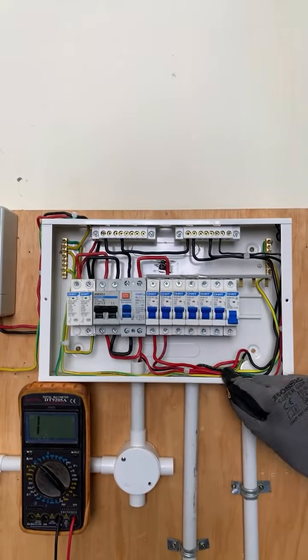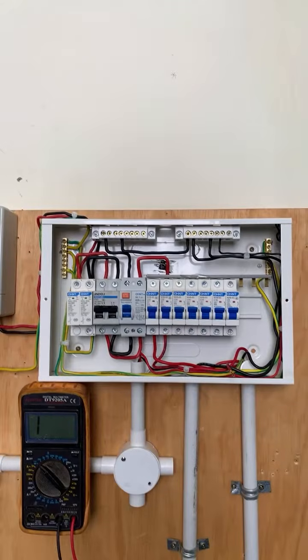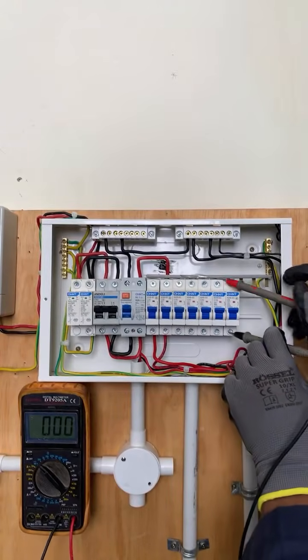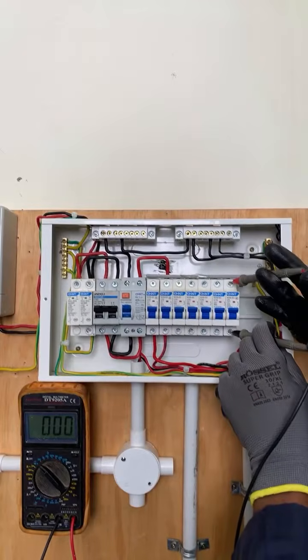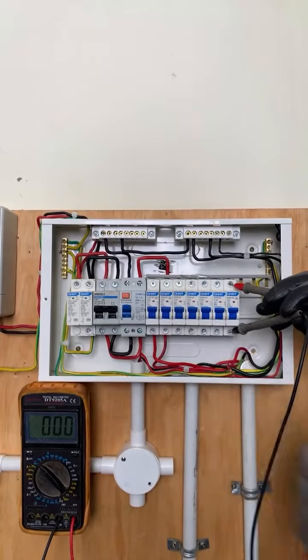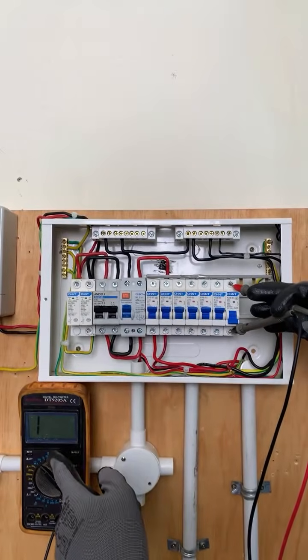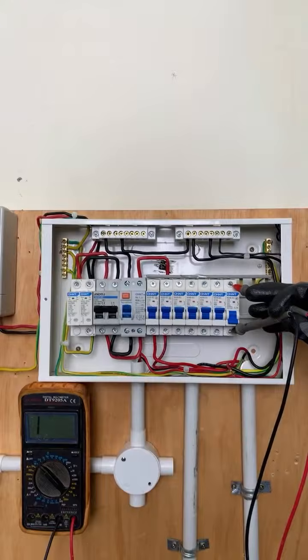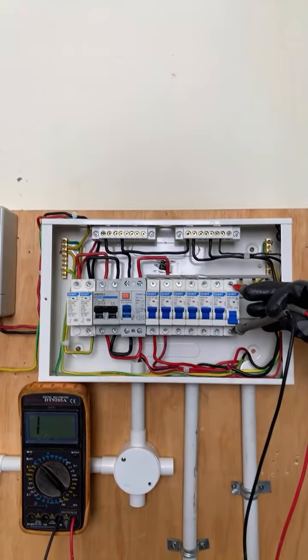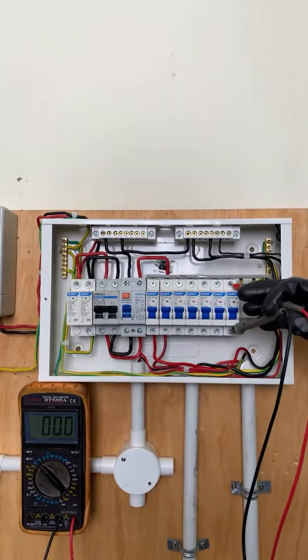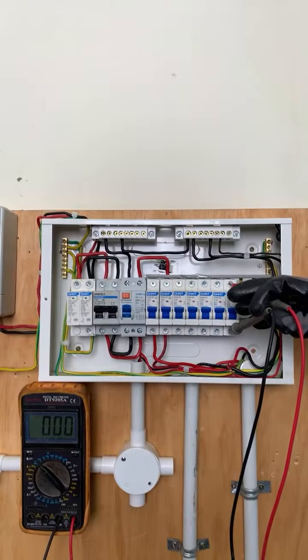Once you have isolated this circuit, you can switch the MCB on because it is not connected to any circuit, and then you can test for the continuity of that MCB. So you place the probes there, and because you are testing for continuity, if you switch it off, you don't have that sound, and your multimeter gives a 1, meaning infinity, right? Put it on, there is that sound. You have zeros, meaning a short circuit, right?